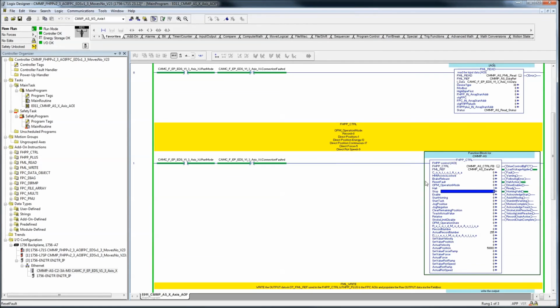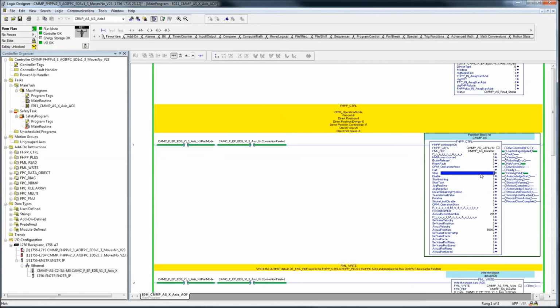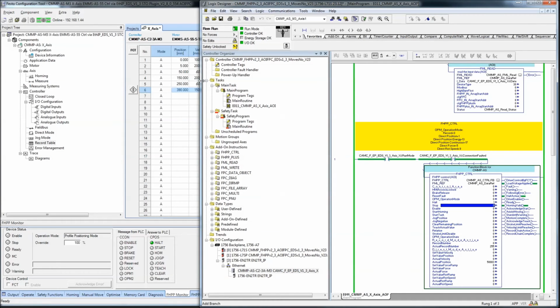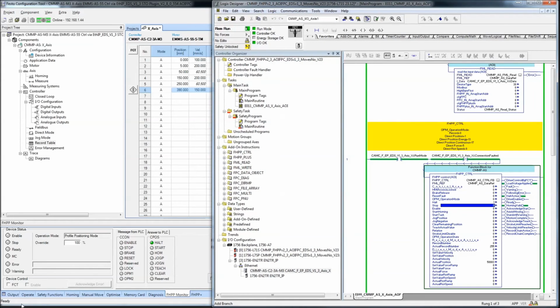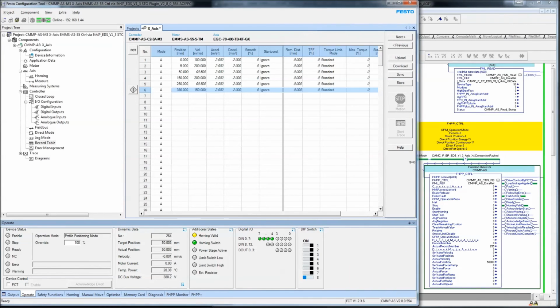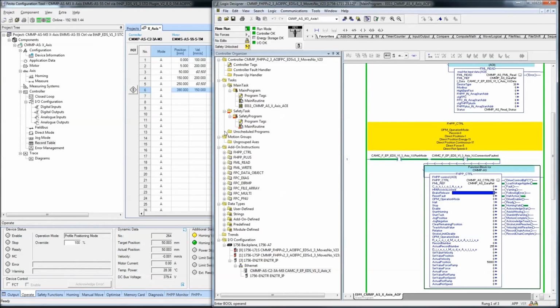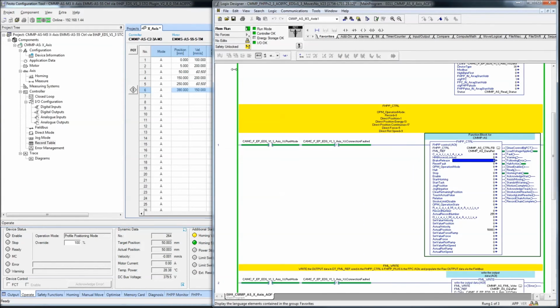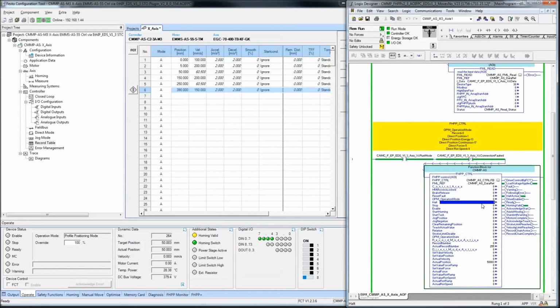I'm going to give you a quick blurb on the bare minimum of running an axis. So maybe I can do something where I can see this over here. So right now I'm going to have you focus on the power stage. Halt. We need to stop, and we need to enable. So as we have those, you have the power stage active, and the PLC is now in control.